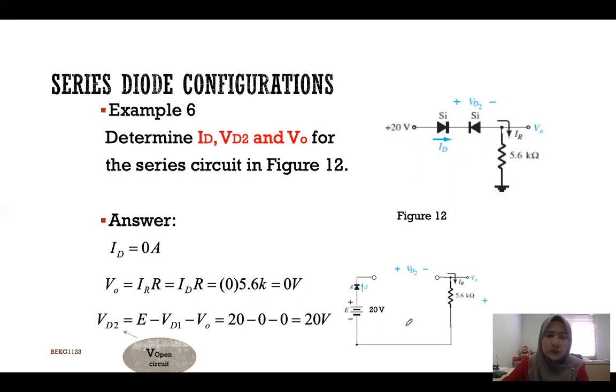If you look here, this is forward bias, however, this is reverse bias. If forward bias, you can just maintain it like this because you have the voltage VD equal to VK. However, for the diode with reverse bias, the circuit here is an open circuit, because it's reverse bias.